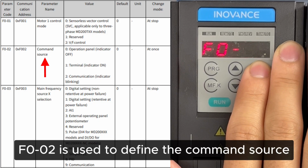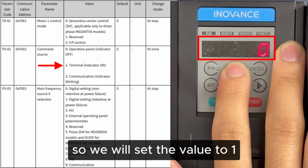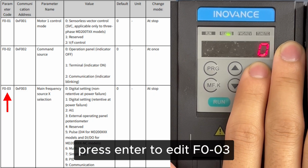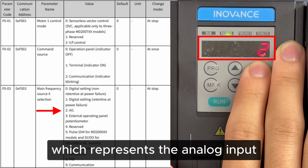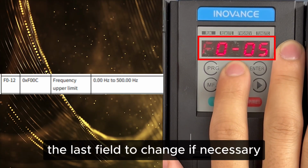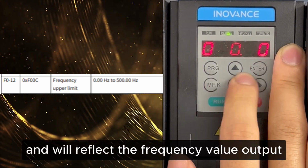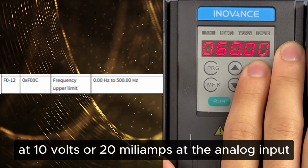Once you have inputted your desired value, press Enter to save and move on to the next field. F0-02 is used to define the command source. We want to set this to our terminal control, so we will set the value to 1 and press Enter to save it. Press Enter to edit F0-03, which controls our frequency source. We will adjust this to 2, which represents the analog input, and press Enter to save it. The last field to change, if necessary, is F0-12, which is the frequency upper limit, and will reflect the frequency value output at 10 volts or 20 milliamps at the analog input.